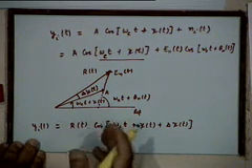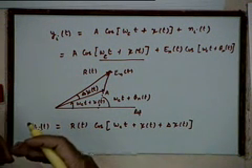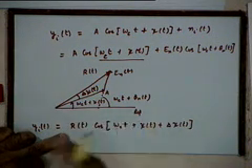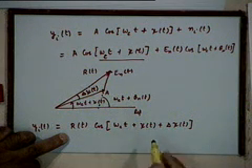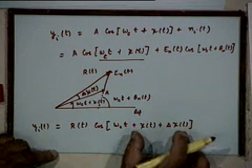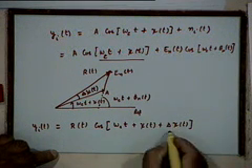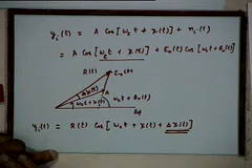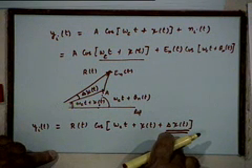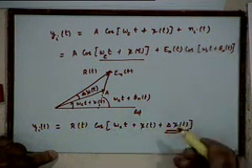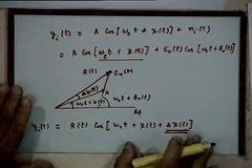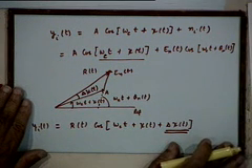The time variation in Rt would not matter, because if you remember, the demodulator will also contain a limiter, so this will be converted into a constant amplitude. This is of no consequence. Really speaking, the angle demodulator will produce an output proportional to the instantaneous angle. So the effect of noise will be obtained by considering the effect of noise on delta psi t, because that is what you should not have got, which you are getting because of noise. And as you can see, it's not a linear analysis.